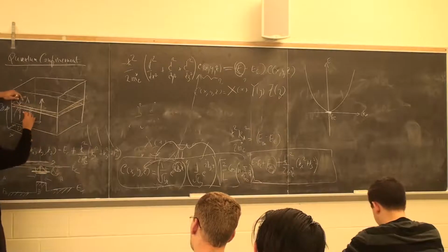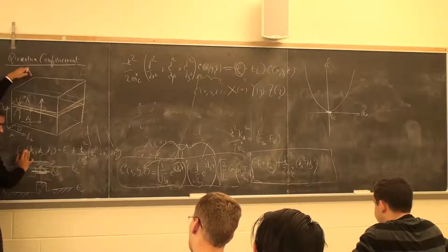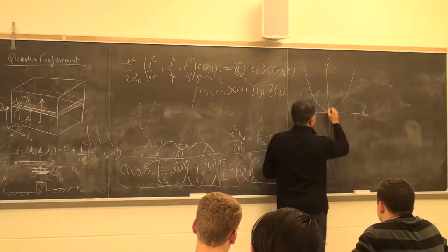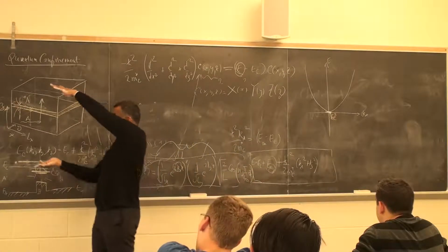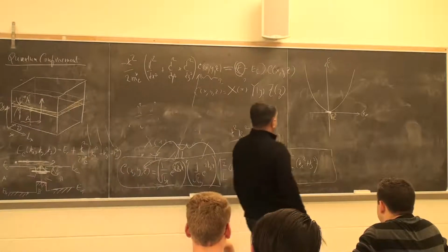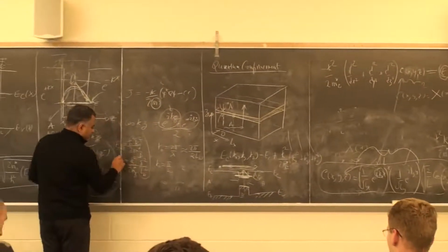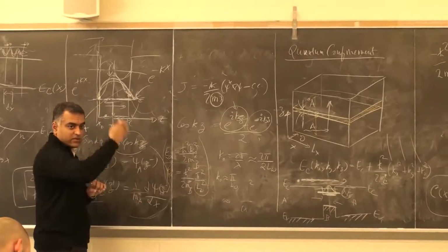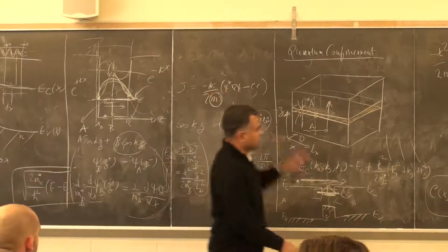Maybe I'll explain it this way. Let's say I had just B everywhere. I didn't even have A. I just make it very wide. In which case, this would be the conduction band minimum of B. That's the minimum energy, and the energies allowed in kx, ky, kz all look like that. And now I make this very, very thin, maybe a 2D crystal sort of thing. It's very thin, and this confines it, in which case the ground state energy will start increasing as the square of the thickness, right? As you shrink it, the ground state energy goes up as the square of the thickness. It increases very sharply, actually, as you go to very thin regions.